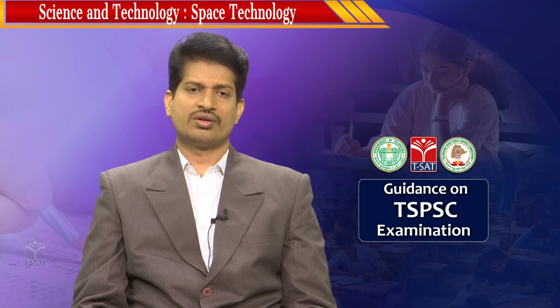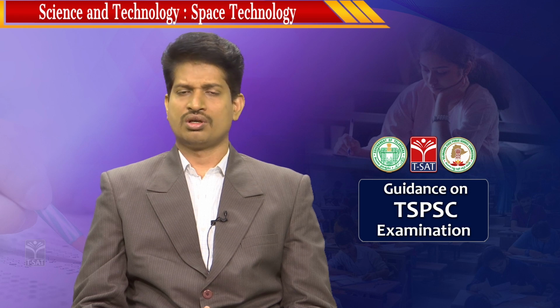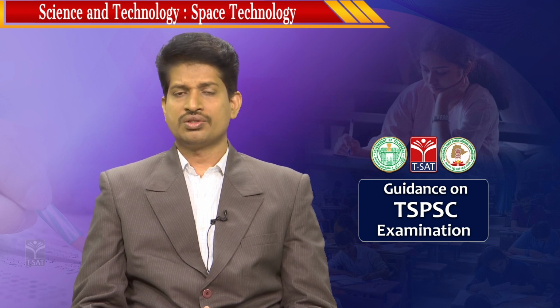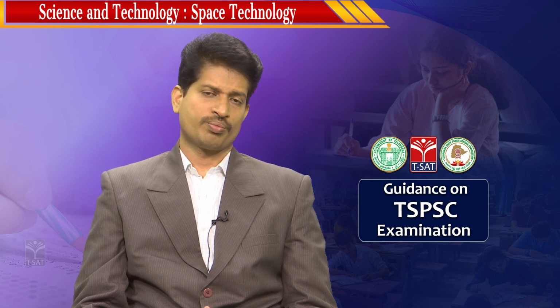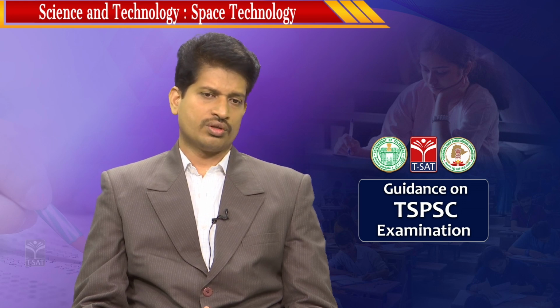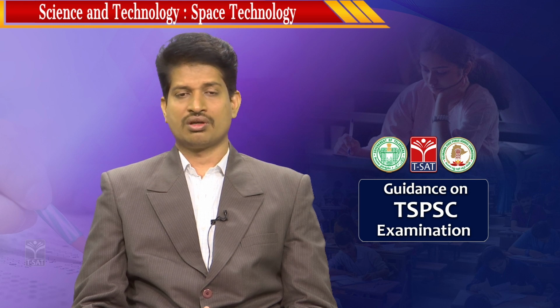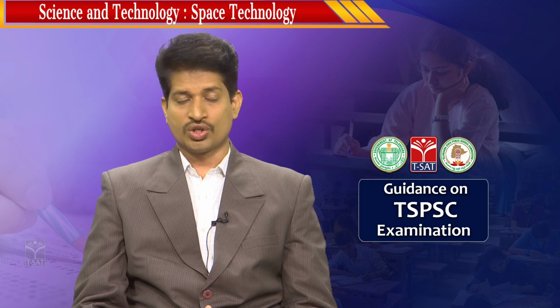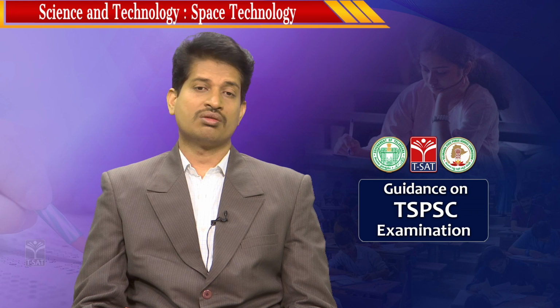The other advantage here is that the time duration of the revolution of satellites in Molniya orbit is 12 hours. So, in a day, a satellite in a Molniya orbit will be able to do 2 revolutions, meaning the orbital ellipticity is set in such a manner that it spends only a couple of hours in the southern hemisphere, and the rest of the 10 hours in the northern hemisphere, so that a satellite is available to the northern hemisphere for 20 hours in a day.